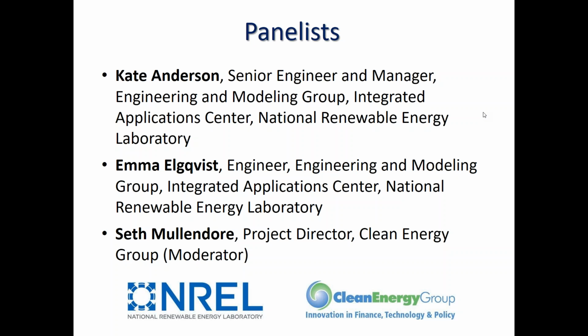Yeah, good question. So right now, the defaults are set to represent a lithium-ion battery, but you could absolutely change those defaults to represent other technology types. So the basic model still applies, but you might want to change, for example, the cost or the minimum state of charge or the maximum state of charge to represent other battery technologies.